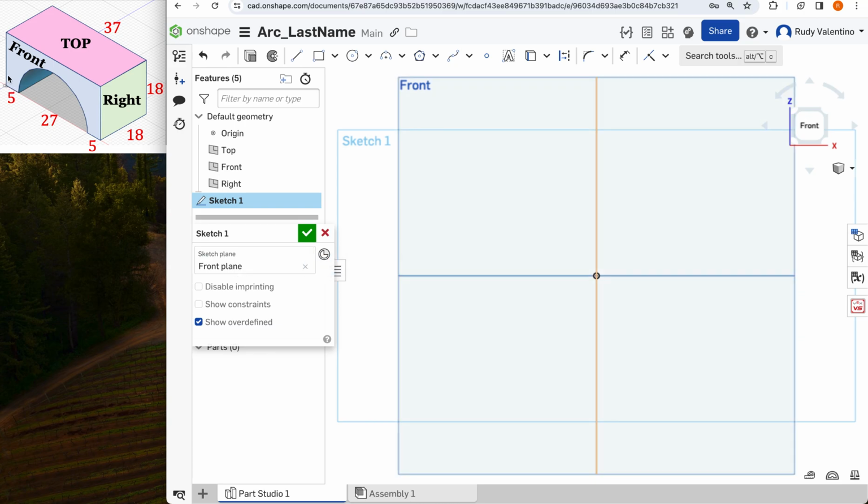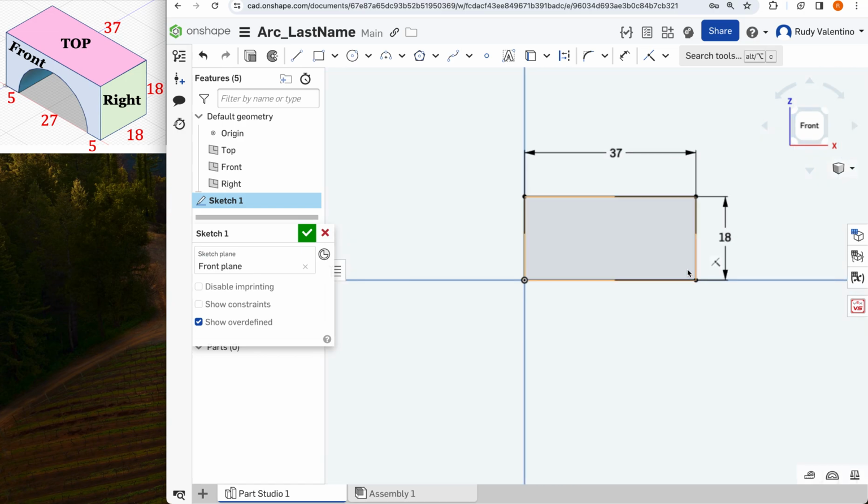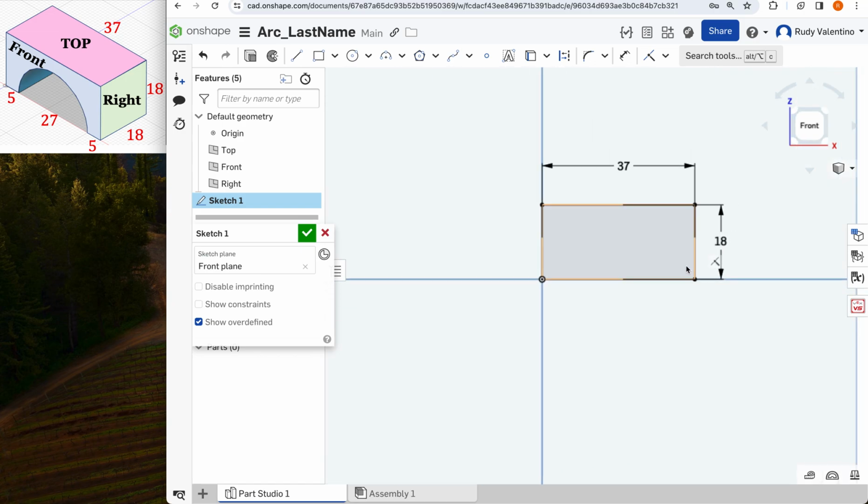So the first thing I'm going to do is I'm going to create this rectangle, and I know it's 37 millimeters wide and 18 millimeters tall. So I'm going to go over to a corner rectangle. I'm going to click on my origin, and then I drag it up. I'm not going to get it exactly, so I just click somewhere up there. I'm going to click 37 across, hit the return or the enter button, and then I'm going to be 18 units high, and I'm going to enter. Now, I'm just going to hit escape so I could pull this out of here and it looks a little nicer. Since I'm going to put a circle on the bottom, I pull this up. Things you don't have to do, but I am going to zoom in a little bit. All right, oops, too much, so I zoom out.